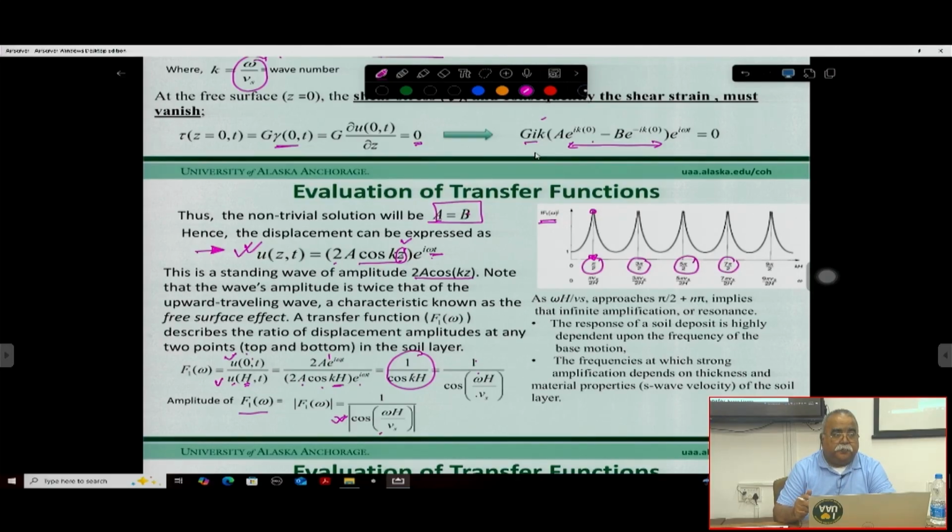Make sense or no? In this case, the peaks are the same for all waves, because this is a single layer. If you have 2, 3 layers or more, then it depends on the layers. But the predominant period is what we will be looking for, which means the first fundamental frequency, and from there we can calculate the other things.